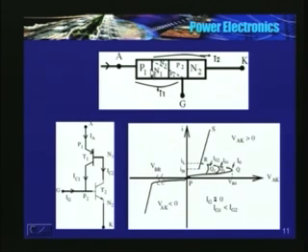See, I told you there are 4 layers: P1, N1, P2, N2. Now what I will do is, I will cut this and this. So N1, P2. Now what is this? Say here, P1, N1 and P2. Now this forms a PNP transistor.